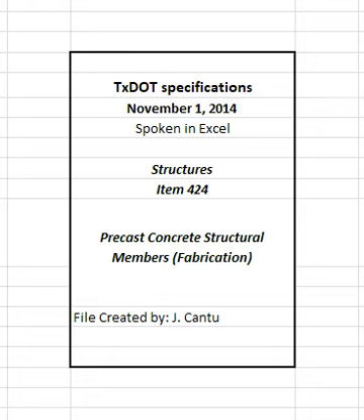Self-consolidating concrete, SCC. A highly workable concrete that can flow through densely reinforced or complex structural elements under its own weight and adequately fill voids without segregation or excessive bleeding without the need for vibration. Temperature probe. Thermocouple for measuring concrete temperature or air temperature. Temperature recording device. Data logger for recording temperatures from the temperature probes.